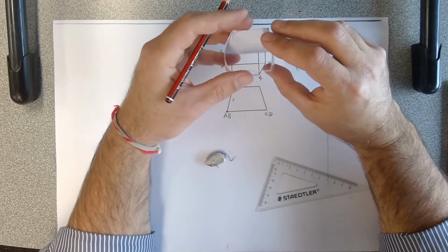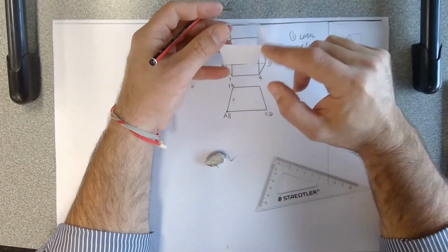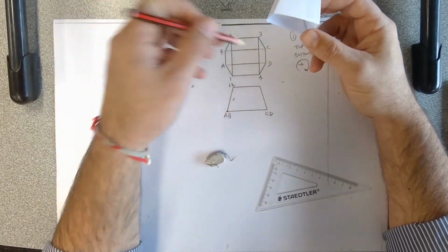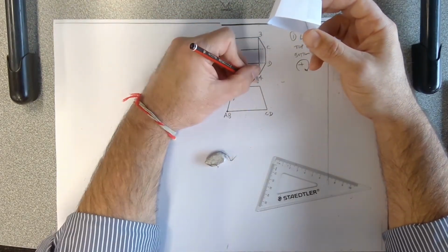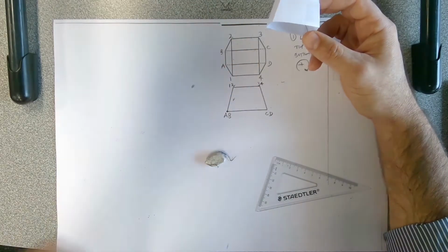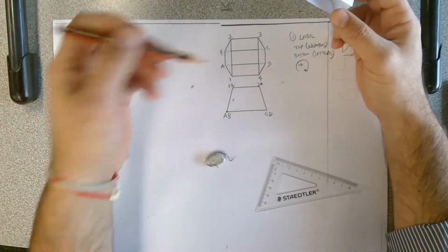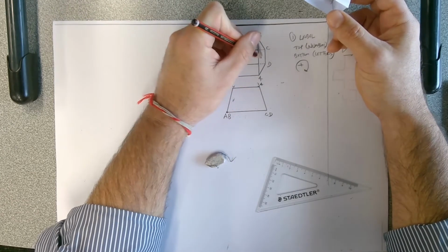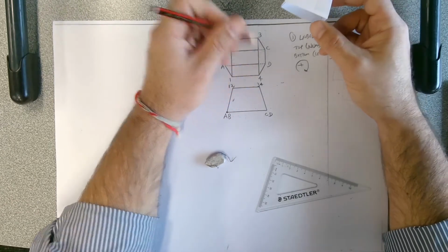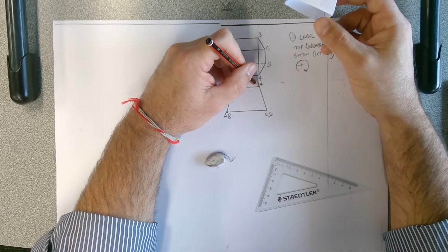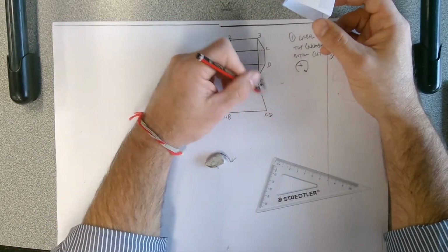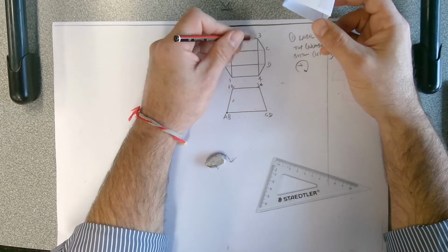Down here, CD, once again, we know that the CD is the bottom here, but when you look at that view, it's going away from you, so it becomes a point. Okay, and then the top becomes 3, 4. Now you've got to remember, one of the rules here is if it's a point view in one of these views, then in the other view it is a true length. So point 3, 4 is going away from you. It's a point going away on this bottom view. So in this top view, that's a true length.